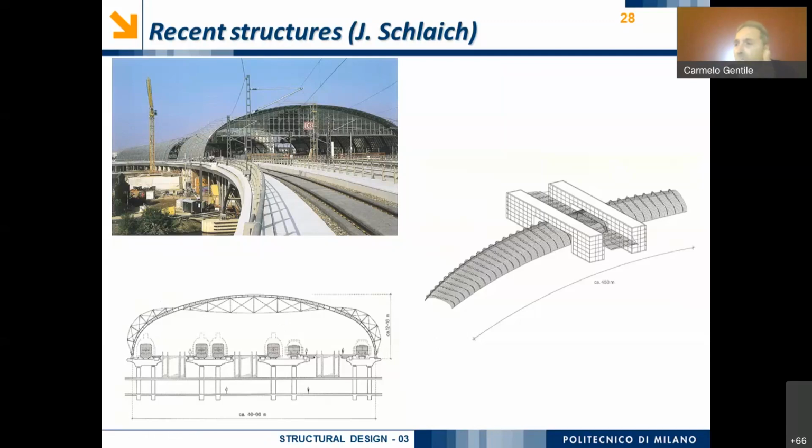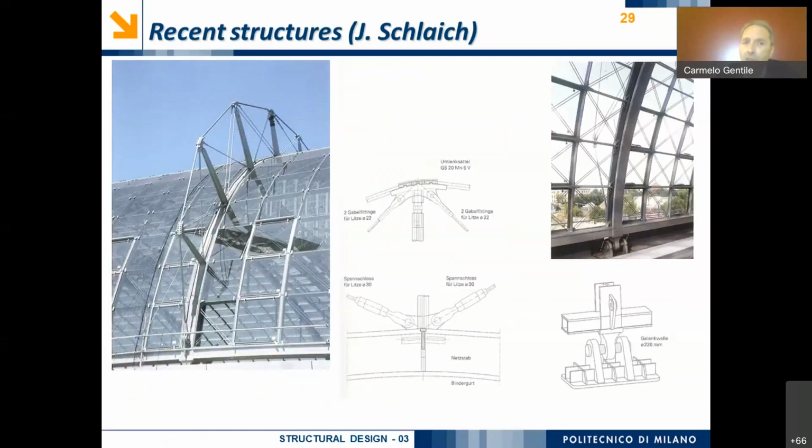Ruccolo showed you in the second part of this lecture of today. And in this part, there are the fibers in tension. So there is a strengthening by using a truss girder in this part where the fibers in tension are the inner ones, and in this other part where the fibers in tension are the outer ones. So this is a typical example in which there is a clear superposition between architectural objective and engineering objective.